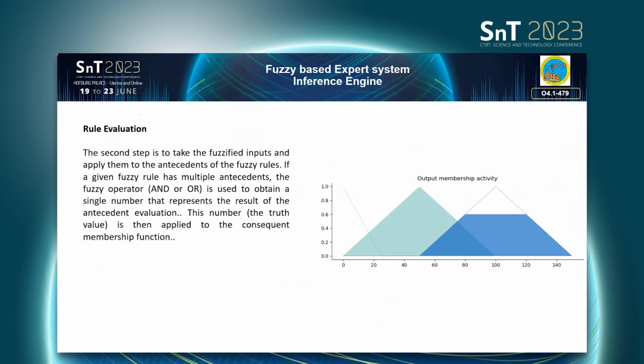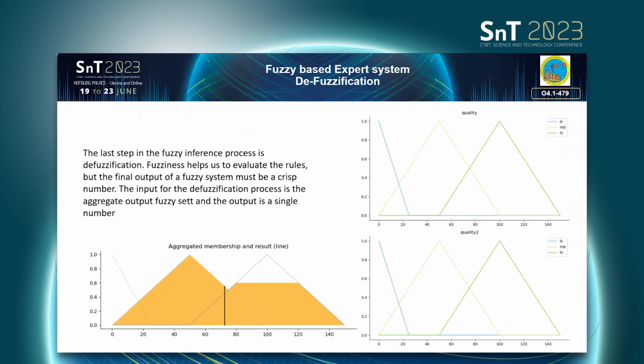The final block in our fuzzy model is the inference engine, which has a great role in merging the rules and firing them based on the values, and then the defuzzification part, which is responsible for converting back from the fuzzy domain into the real world domain and calculating a single value as a quality parameter for each output parameter, which will be the final decision for the quality.